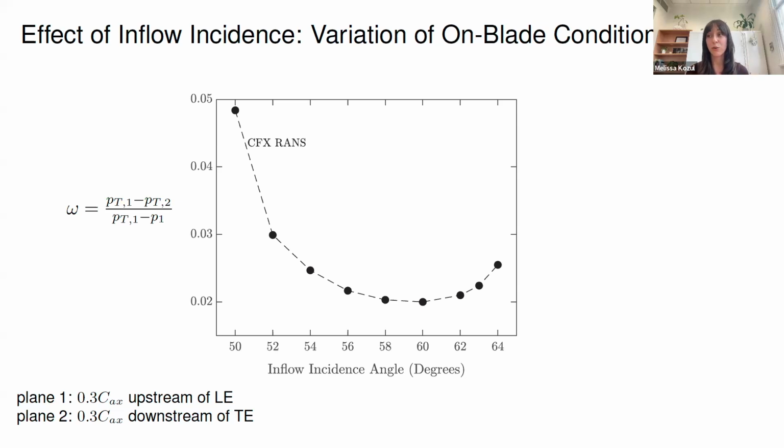This is also relevant for terrestrial gas turbines because when we ramp them up very quickly, as I was talking before, to be used as peakers in the grid, this is also going to be a misalignment of the incoming airflow to that compressor blade. And so engine designers are also very interested in looking at what we call off-design inflow angles. So we can't just look at the design angle, but we need to look at either side of this, positive and negative, to see how that blade performs over that full envelope of expected incoming airflows.